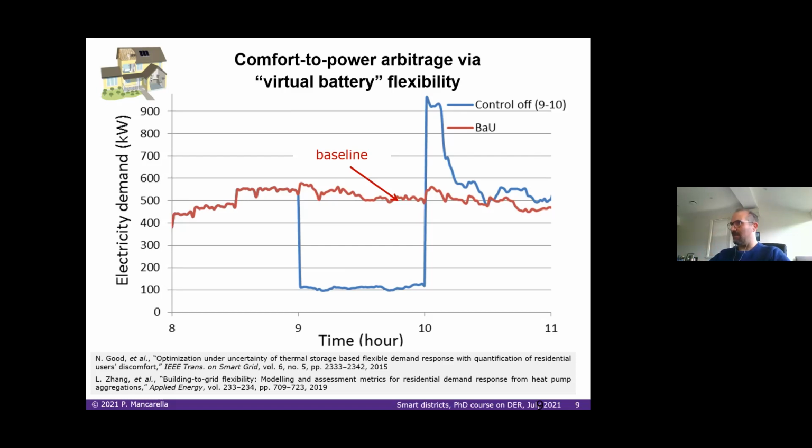It's done with modeling, but we were really doing it for a proper demand response study in London, probably 2009, 12 years ago. That was long ago, but things haven't changed much. So imagine you have a baseline consumption for your air conditioning system in this commercial building, probably for cooling. Yes, also London requires some cooling sometimes. And then you want to switch it off. You switch it off because you rely on thermal inertia, so the temperature doesn't go up too much.